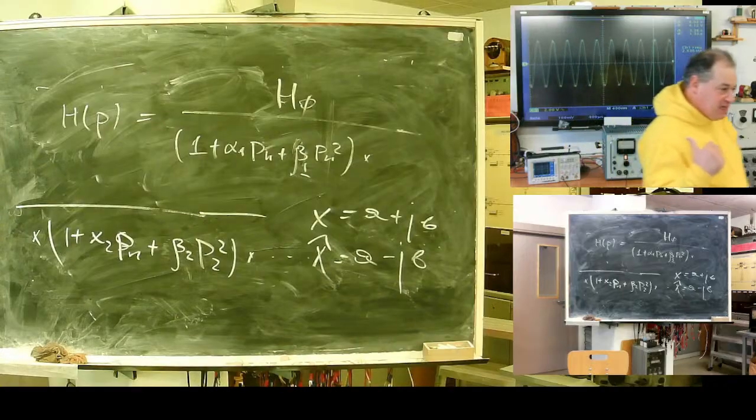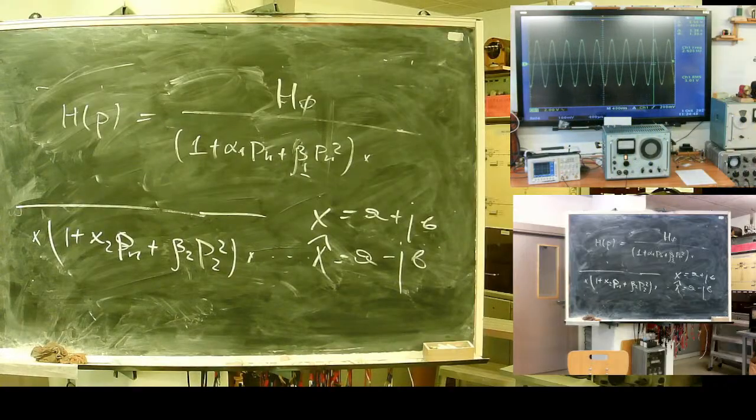It's a budget design. If you deal with high-end generator protection or high-end fault location, the budget will allow it, and you can afford an active tunable filter for each channel. This one has a set of passive filters and only one op-amp for all, the switchable model.